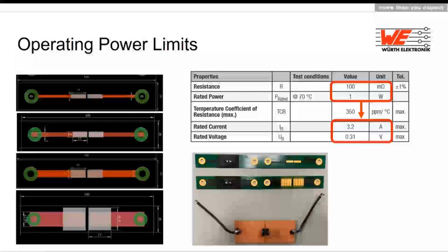Going from top to bottom on the left side, we have our 2 ampere version of the rated current board, then 3 amps, 7 amps, and lastly, with also a lot of wires, a 22 amp version. When you expect higher currents, we have, of course, pure copper PCBs, like you see here in the right picture at the bottom. When you have a closer look, you also see the resistors already mounted on some PCBs. They are painted black to have a better temperature measurement.